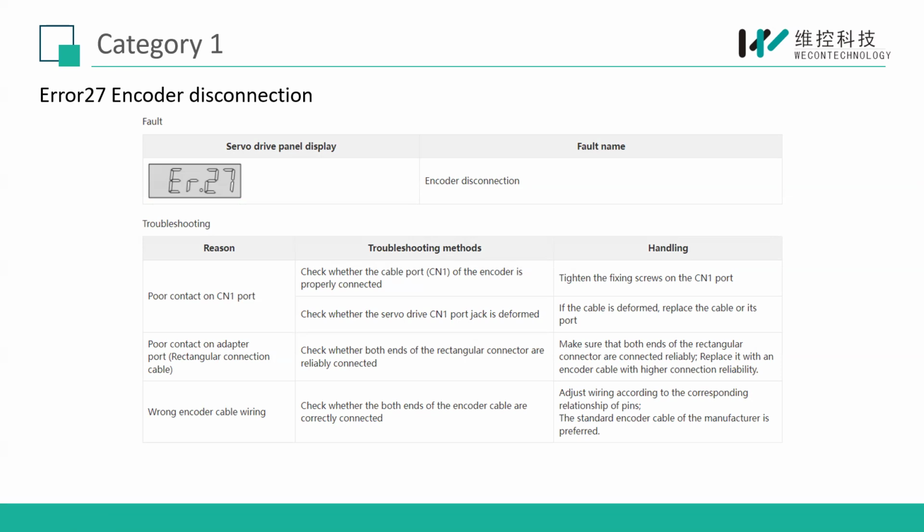If the cable is the problem, we can directly change to another cable. If the motor side or driver side has a problem, we need to check the connector terminal to check whether it is damaged or has some connection problem. Maybe the connector is too loose. So we need to check it. And for this error, usually it is a hardware side error. It has nothing to do with our firmware.